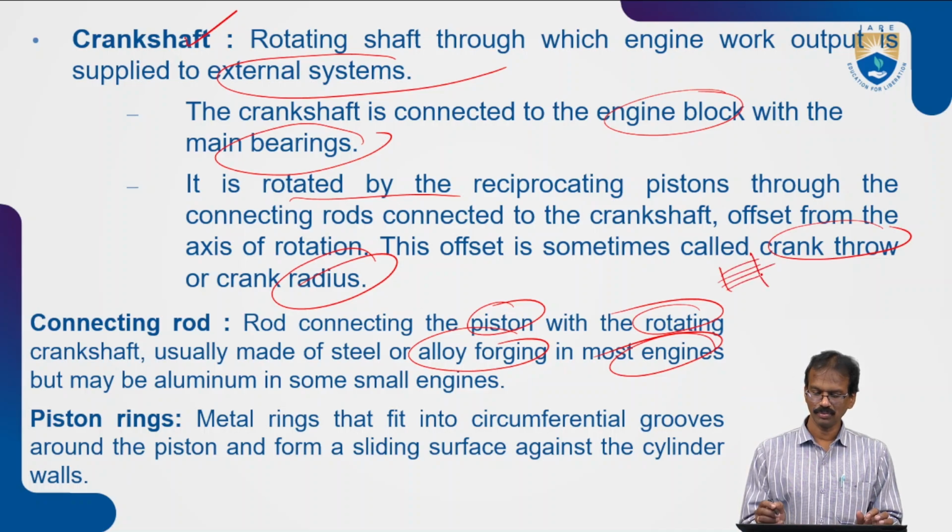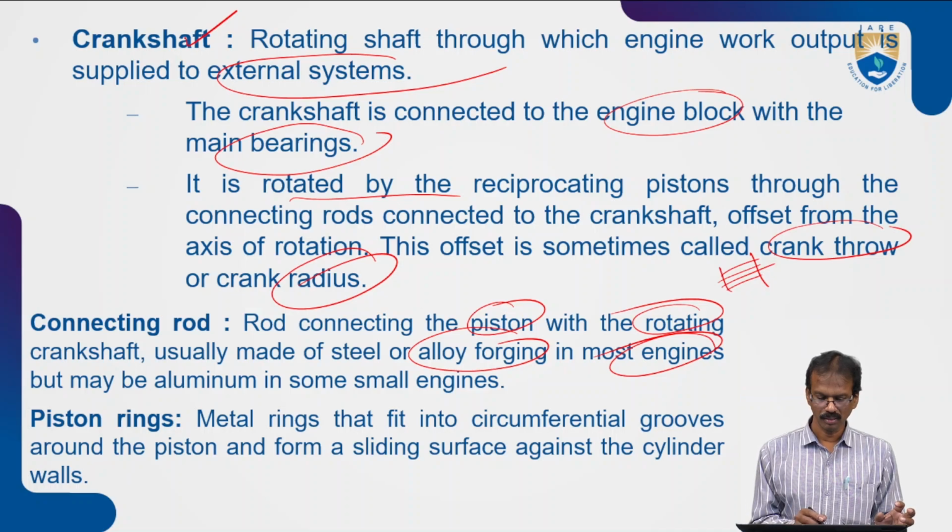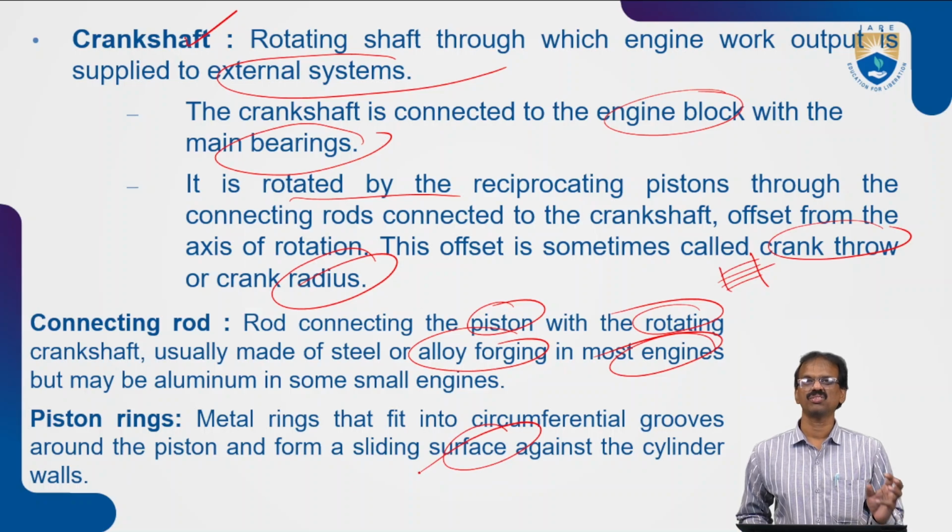They give tightness between the piston and the cylinder without any leakage of charge, and they form a sliding surface. So for the sliding surface, we use piston rings.